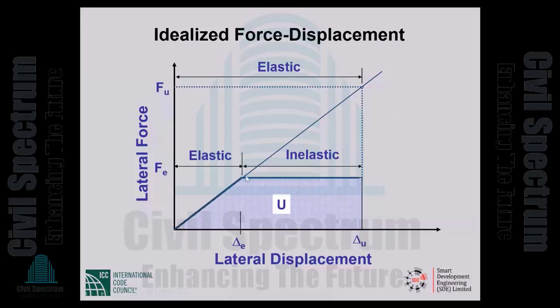And initially, we are showing elastic response. Elastic response does not have to mean force proportional to displacement as shown. Elastic really means no residual displacement. The earthquake passes, we get our structure back intact. And importantly, located where it was before the earthquake, not some distance away from where it was. Okay. No residual displacement, meaning no damage to be repaired. We get our structure back intact.